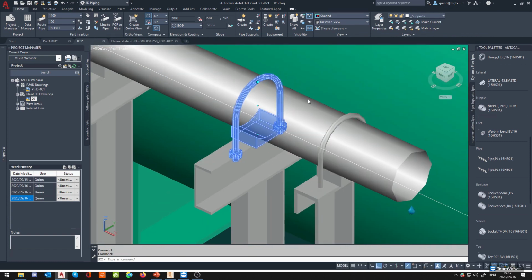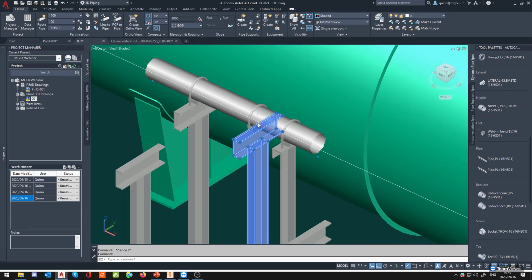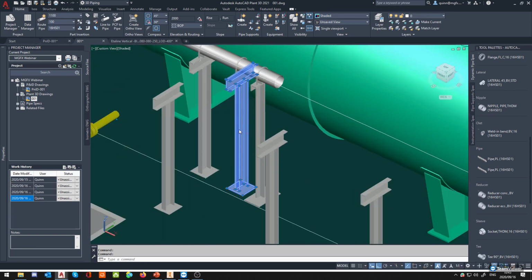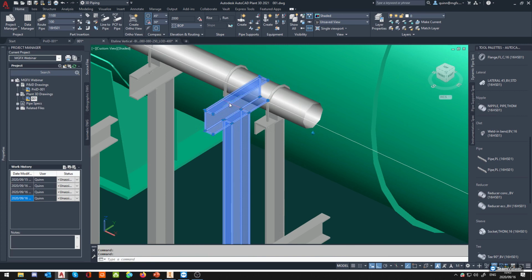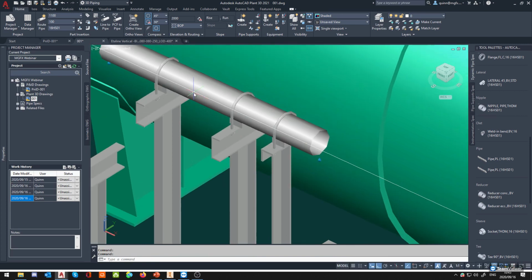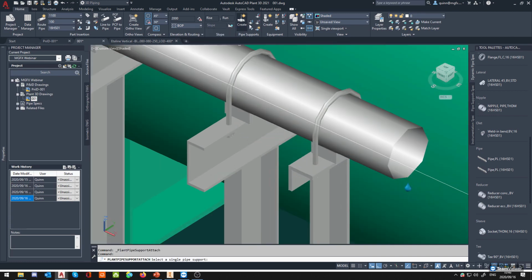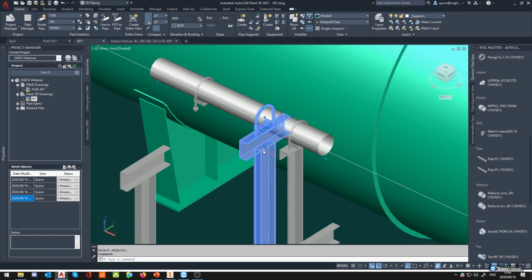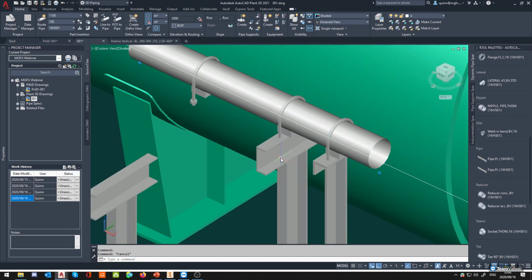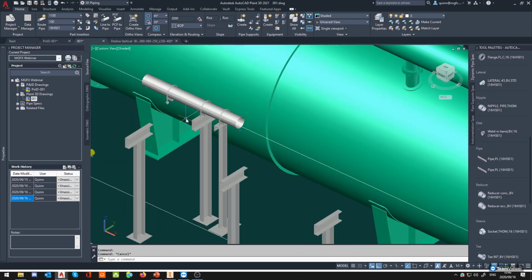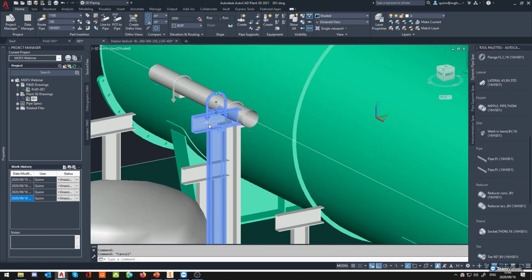So this is the stock default plant pipe support, but with our 3D drawn-in support over here. You're going to say, hey, Quint, okay, that's a nice pretty picture, but it's not technically a pipe support. If you notice, this one actually is. It's because there's this little cool thing over here which we can attach stuff to the support. So we use the detach button, select the support, select the other item, and voila, it creates it into one support. Oh, I did something over there that you didn't like. But apart from that, it's just a visual glitch. You can actually see it's still there.